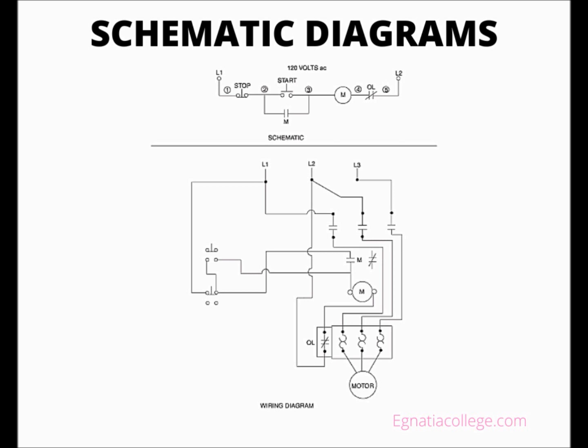Schematics are commonly drawn for electrical equipment that involves internal wiring, everything from washing machines to computers. A basic motor control schematic shows a 3-phase power source, L1, L2, and L3, through the starter contacts, M, and the overloads, OL, powering the motor. The starter control is taken from phase L1 through a stop push button, a start push button paralleled with a latching contact M to the starter coil M, and finally through the normally closed overload contacts back to phase L2.